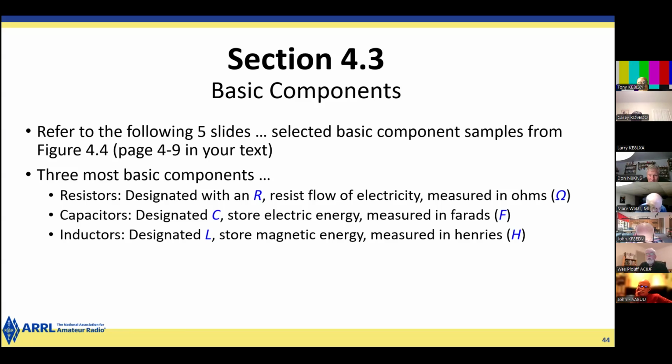Inductors are designated L, and they store magnetic energy, and they're measured in henries. And again, 1 Henry is a fairly large unit of inductance. So you're more likely to see practical components with values of millihenries and microhenries.